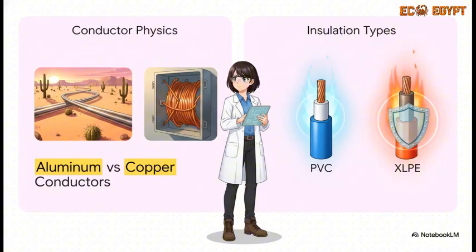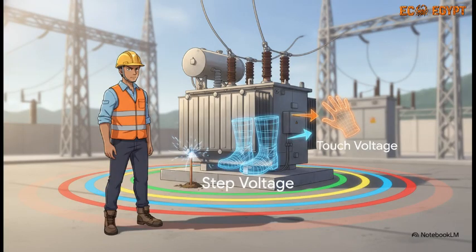Is standard PVC enough, or do you need the 90-degree thermal limits of XLPE for heavy-duty applications? This isn't just an electrical choice. It's a massive financial one that sets your capital expenditure budget. Which brings us to grounding.